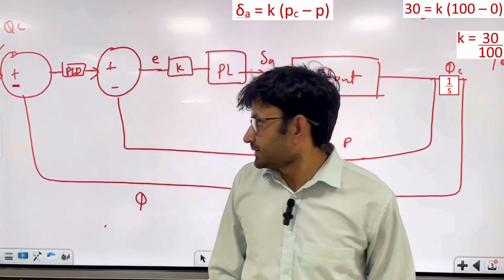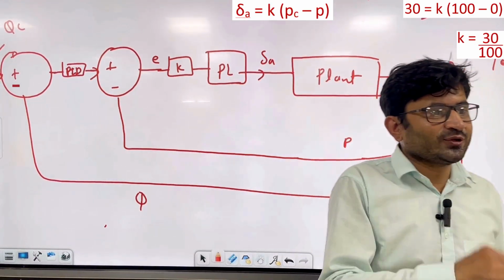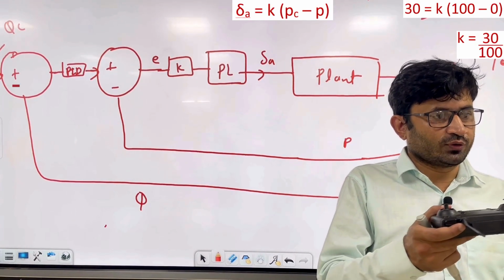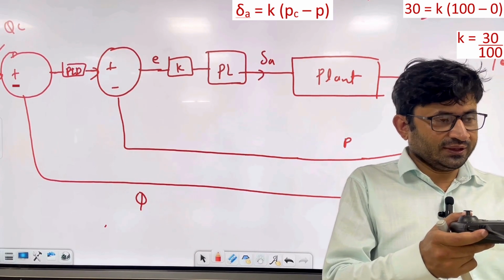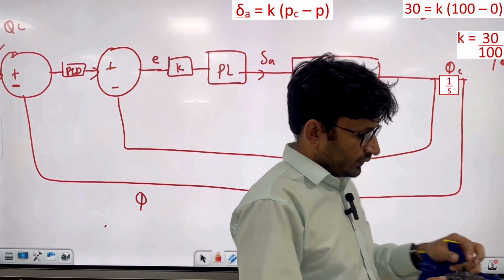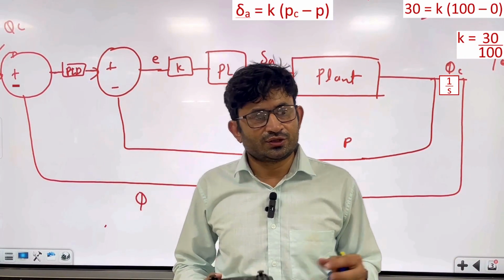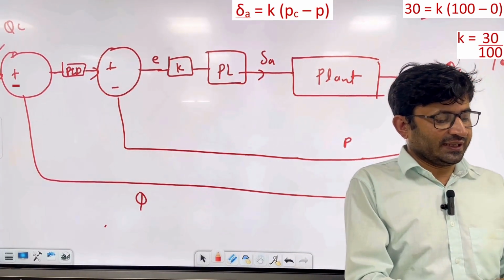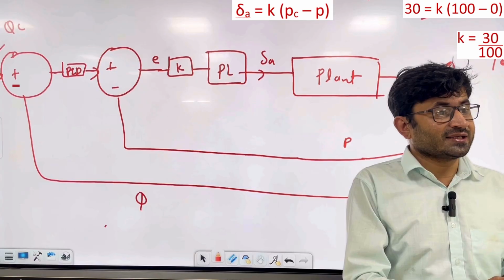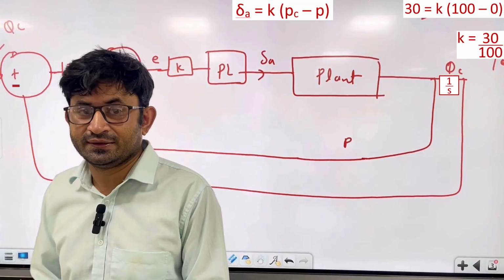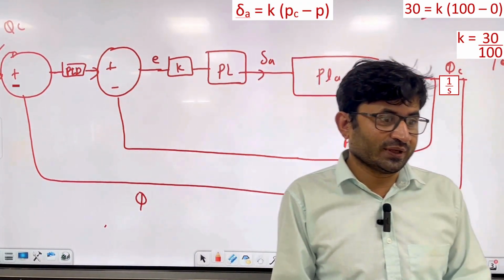So let's say if your stick is at a neutral position, the angle commanded will be 0, and when you move the stick like this, that can command the maximum bank angle. The maximum angle you have set, for example 60°. Okay, so 60° you can command.